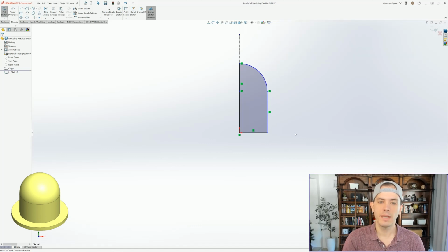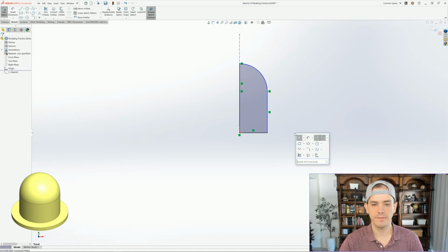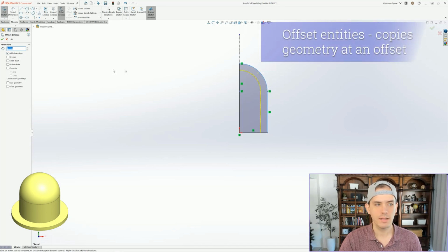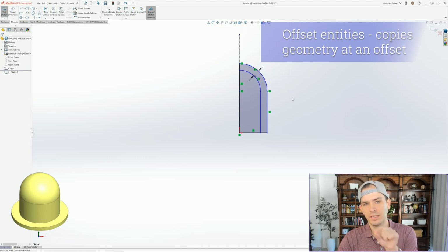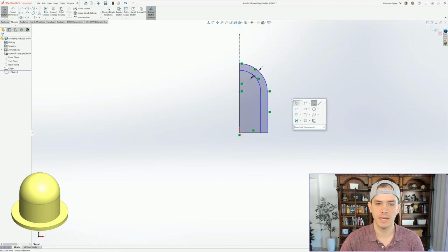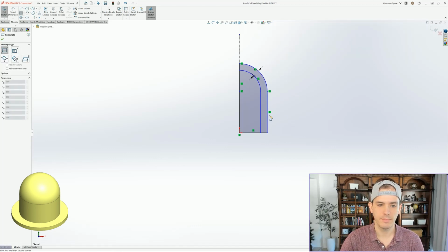All right. So now I'm looking at this view here, this model, and I see that it actually has the offset in there. So I'm going to draw that offset in because, hey, another pro tip here. Again, like I said, modeling competition, 0.25. All right. If they show it, you should draw it, because there's a reason why. They give you the minimum possible. And if it makes it into a view or into a dimension, you have to create that geometry. All right. So keep that in mind.